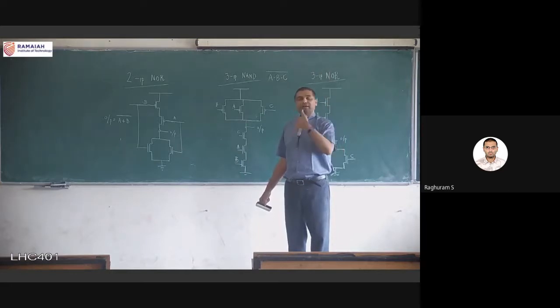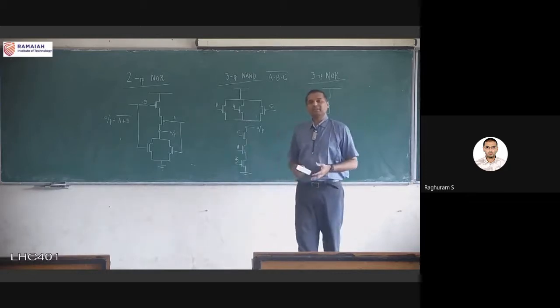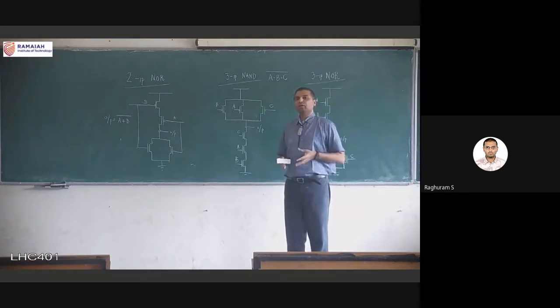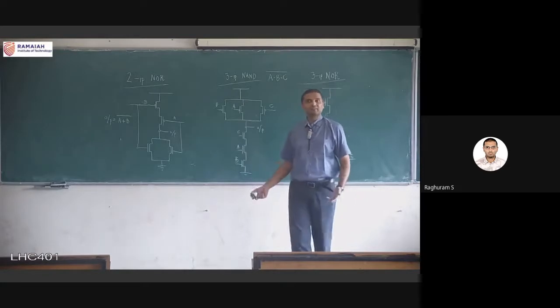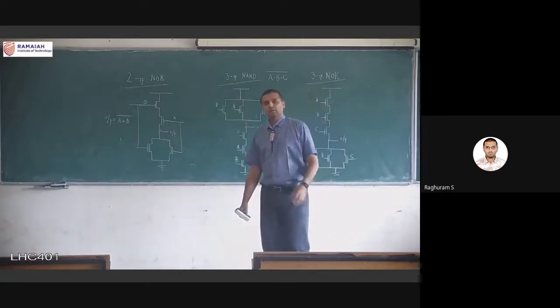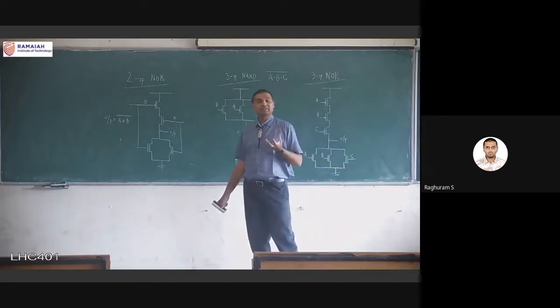As we will see in the 4th unit, the reason it is done like that is that it is actually faster. It is more efficient in terms of speed to have 4 input and 2 input gates rather than one big 6 input gate. Even in the standard cell library, if you remember from the VLSI design flow, one of the most important components of modern VLSI design is the standard cell library.